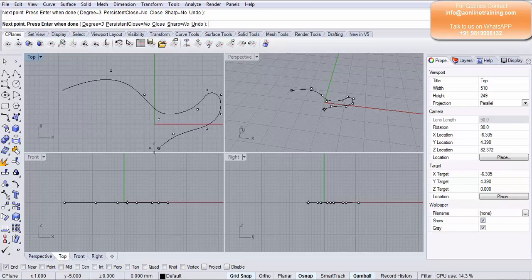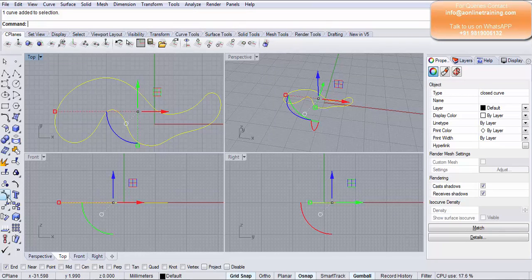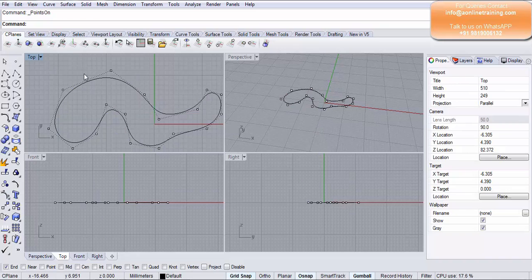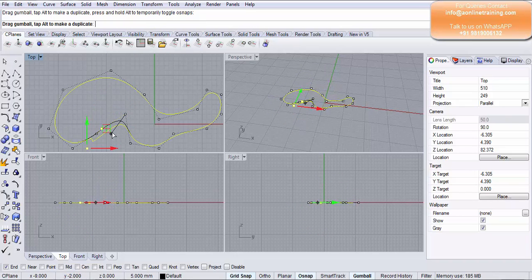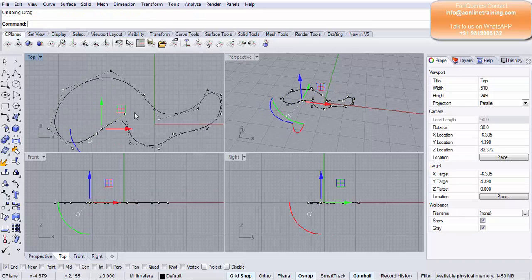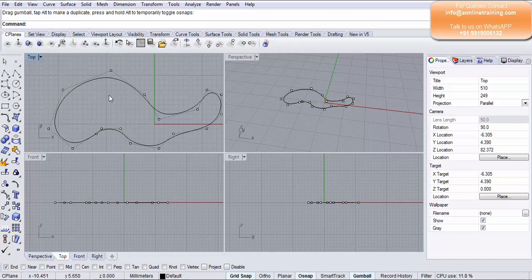As you're going ahead, you're creating the curve. And I go to the point and I click. Again, I just make sure that O snap is on and end point is on so it snaps. I select the curve. I come up over here and switch on the points so I can see the entire points up over here. I can click and I can make modifications. I can get this down, I can get this, there you go. So just a Control Z, I click this point, I get this particular point down, click outside.